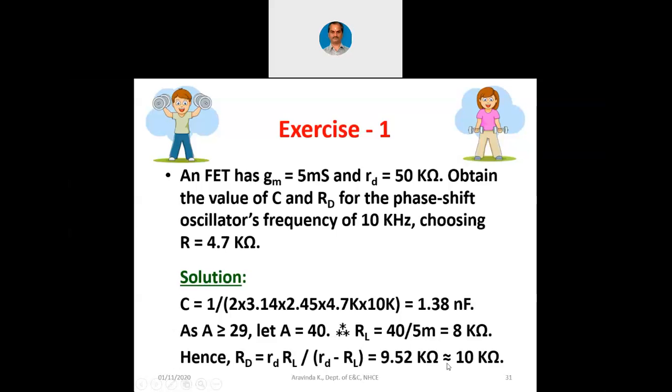So the nearest standard value for the drain resistance is 10 kilo ohms. Now you can observe here, I have chosen A to be 40, because of which I am getting this answer. If you choose A to be 35, you will get a slightly different answer. You can choose A to be 50 also. You will get a slightly different answer, because these are basically designs which we decide.